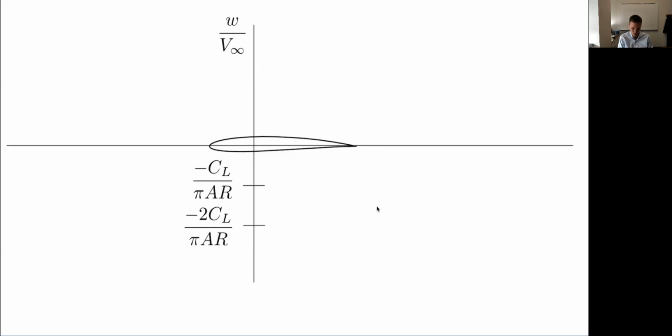Sorry, I'm flipping through a lot right here. So this is what we computed. This is the downwash right here along the wing from all those trailing vortices. So it varies from 0 far away and approaches this value here, which we computed. Although we didn't compute it very far downstream, you could guess what it is. When I'm here, the contribution is from a bunch of semi-infinite vortices.